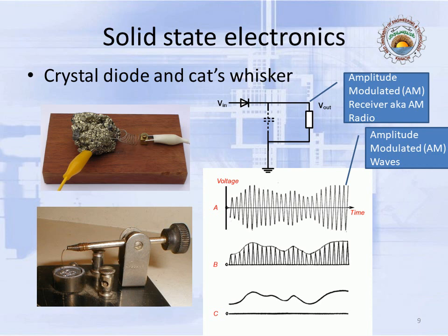So how does that happen? Basically, I will leave it to you to study the intricacies of the circuit for yourself. But very quickly, I'm going to explain this. You see, this is basically iron pyrite, fool's gold, and then there is a wire attached to it. Iron pyrite is not a good conductor of electricity, so you can say it is a semiconductor. This is a metal. So you see, there is a metal semiconductor junction. This wire works as an antenna as well as a tuning coil, and the signal comes into it.